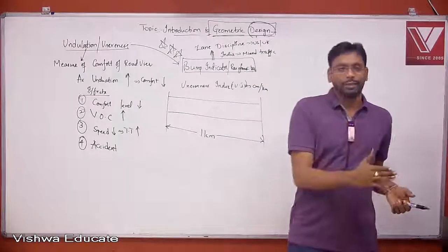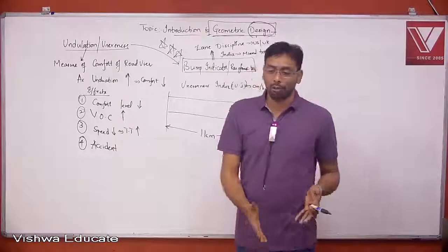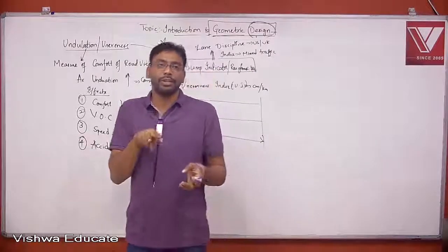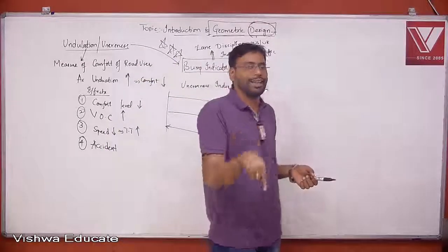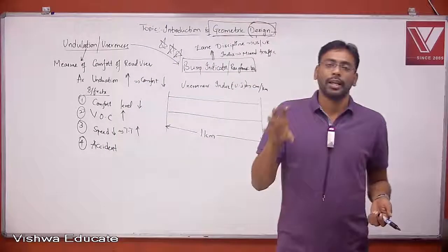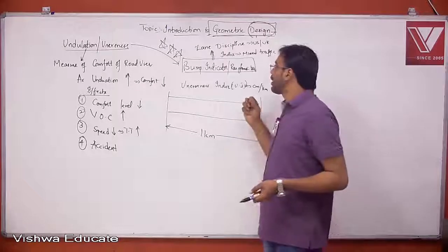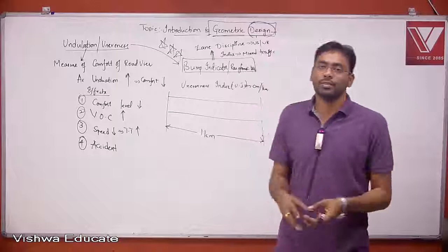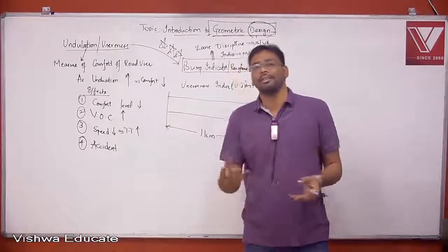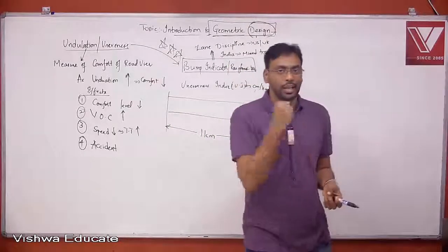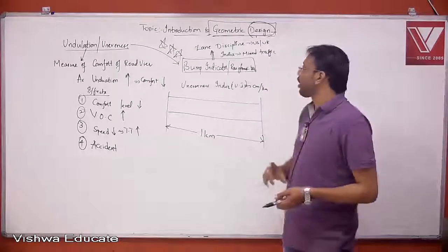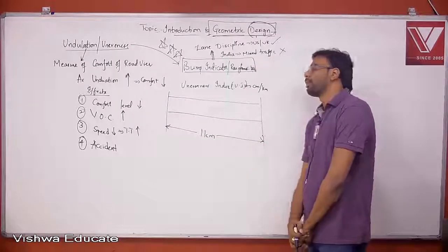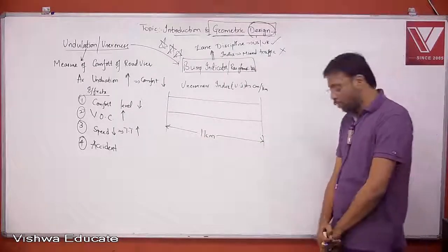So one vehicle will be traveling in that particular lane only. It won't be traveling in the middle of two lanes, or occupy two lanes at a time. It will be in one lane itself. But Indian traffic is mixed traffic. So on the same lane, a number of different categories of vehicles will be moving. So this bump indicator or roughometer is applicable for lane discipline. It can't be adopted for mixed traffic conditions.